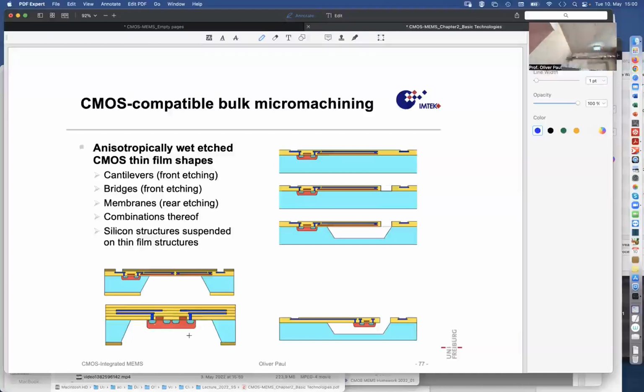If you make it happen that this silicon piece, this N diffusion in a P wafer, has an electrical potential with respect to the solution, by applying a counter electrode and a voltage source, and then a contact to that red zone by the contact lines running over the wafer, then the etchant will etch the silicon, but it will spare this electrically charged piece. It will stop at its boundary, at the boundary of the P-N junction.